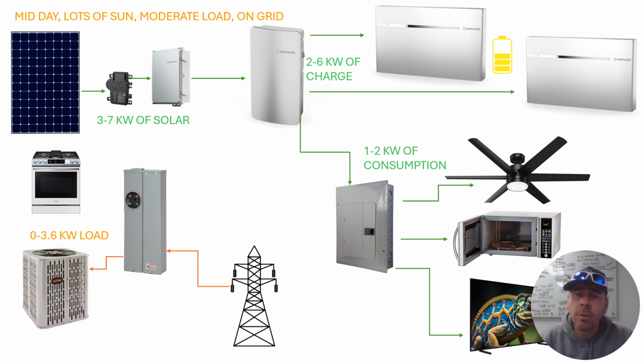It's about half powered. It's been charging all morning, and it's still able to take care of the power if they've increased and stuff like that during the day into the backup loads. It's able to take care of those. And anything that's needed for the higher loads, since they're not backed up and the power is not adequate coming from the battery system, would likely come from the grid. And that's just the way the system is designed and typically in how it's laid out.